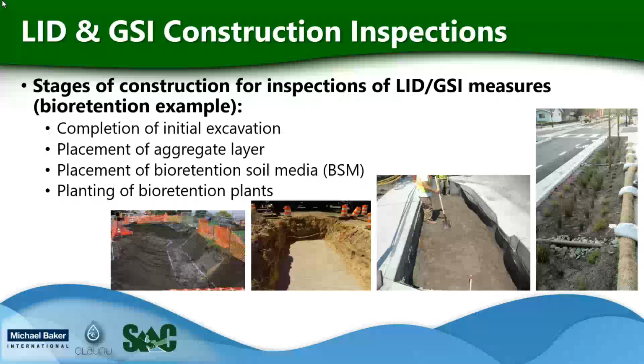At least one inspection should take place, but several inspections are optimal to observe the various stages of construction of an LID GSI measure. And as an example, for a bioretention system, inspection should be completed at completion of initial excavation, placement of the aggregate layer, placement of the bioretention soil media, and placement of the bioretention plants.